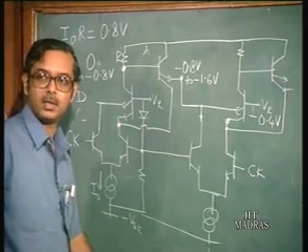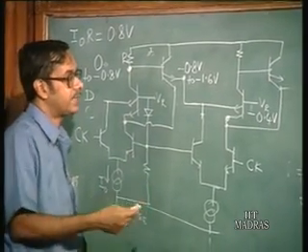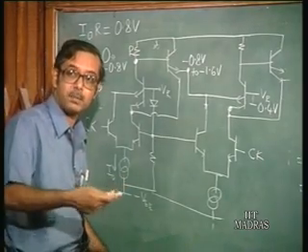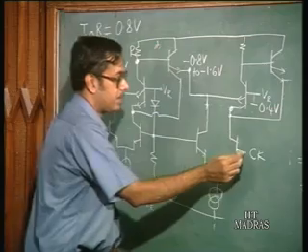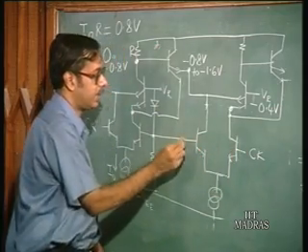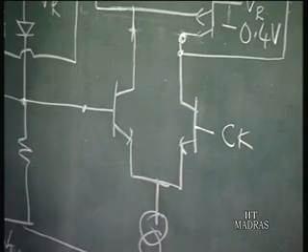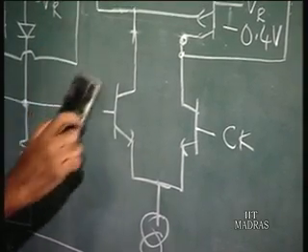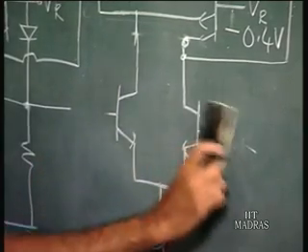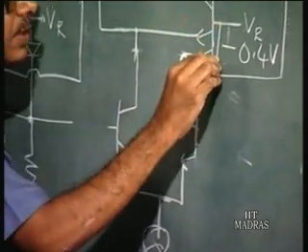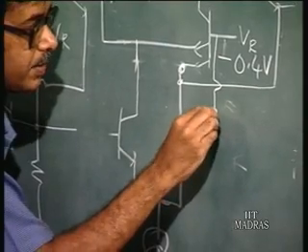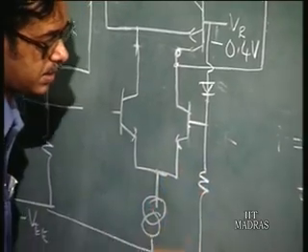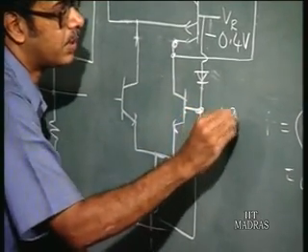Okay. All right. And so, VR minus V on is going to be how much? Again minus 1.2 volts. Okay. So, for the lower part of the stack, let us draw, suppose I think we will take a different circuit. Let us have the normal configuration. So, here you have a diode drop and the resistance. So, this reference voltage is going to be minus 1.2 volts.